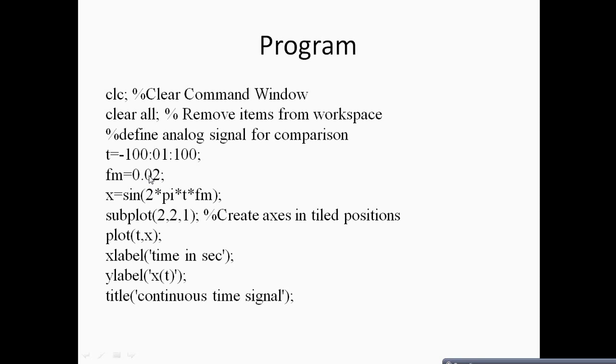and then you can check out the program functioning in the Matlab software. So here with respect to your time domain, that is the scale, we are taking from -100 to 100. It is not mandatory that you take the same time length. You can take anything, or you can even start it from 0 as well. So next, if you want to plot this entire thing, you will be using plot t of x. t is your time length and x is your signal, that is sine 2 pi ft.